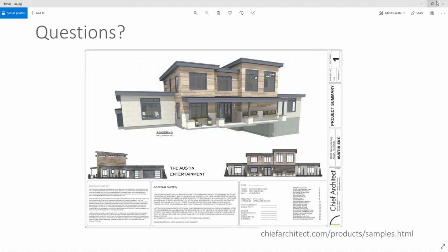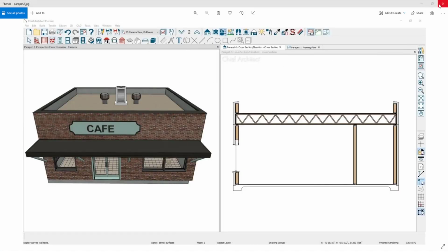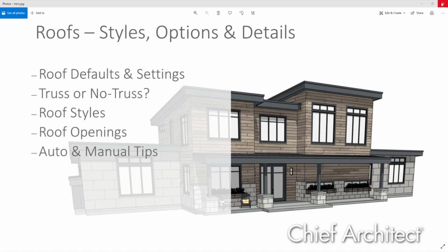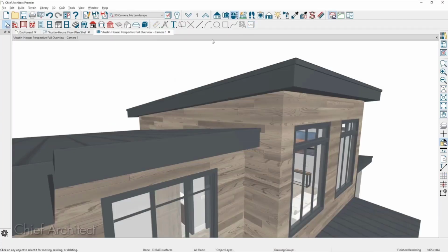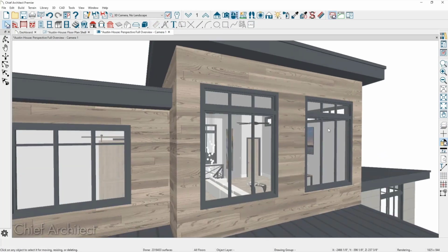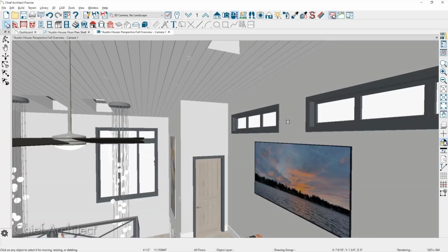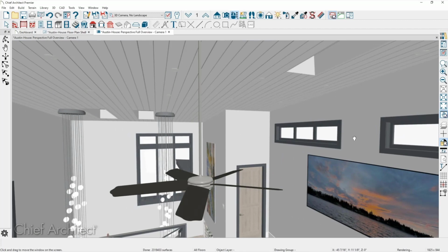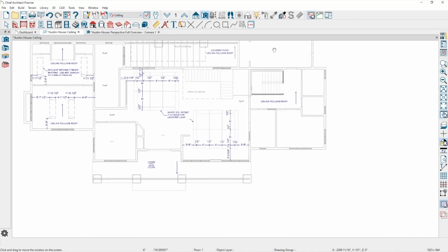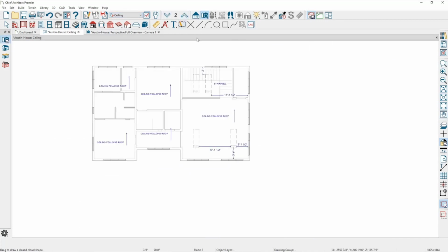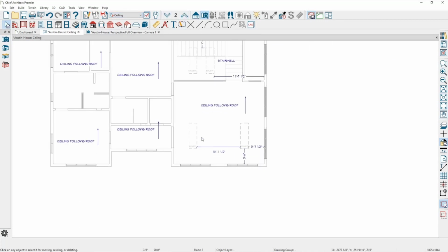So Jason, probably one of the things you could do for that is just use a soffit tool. Let me close a couple of things in here. You could just use a soffit tool. Let me see what I've got going on here. So if I were to come in here and let's say I wanted to put some exposed things in here, you might just use the soffit tool. And if I switch this into my ceiling view, with your soffit tool, you can mark these soffits, and it's under your cabinet tool.